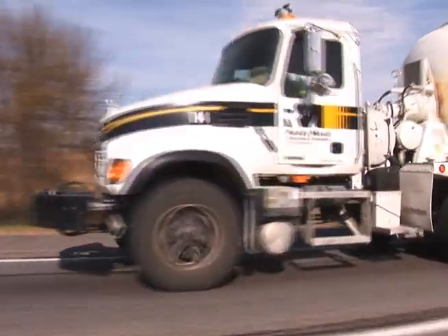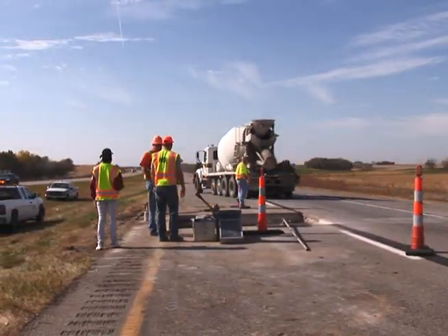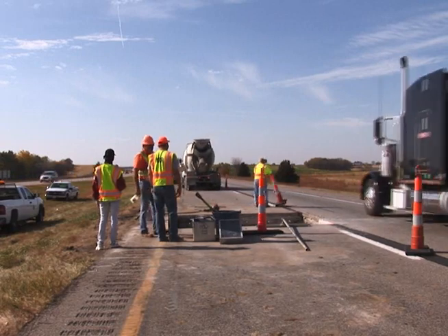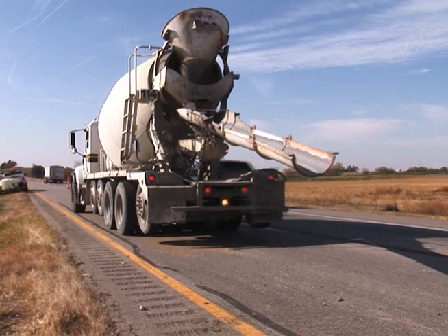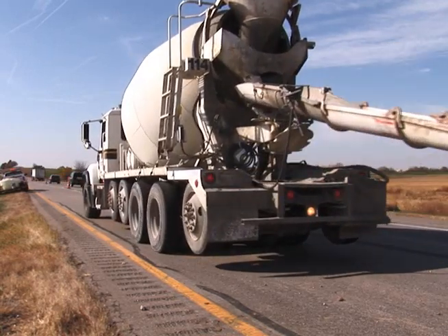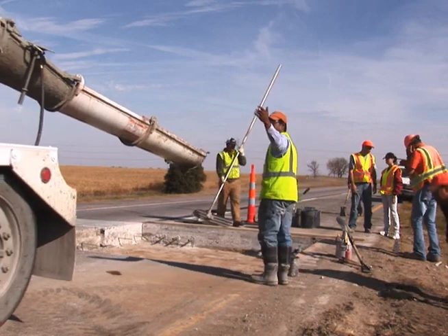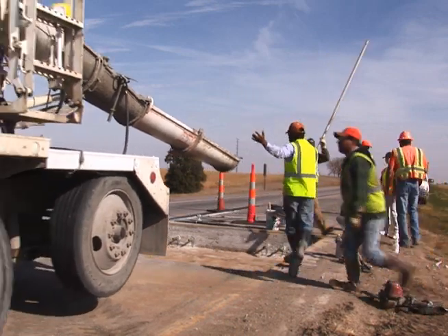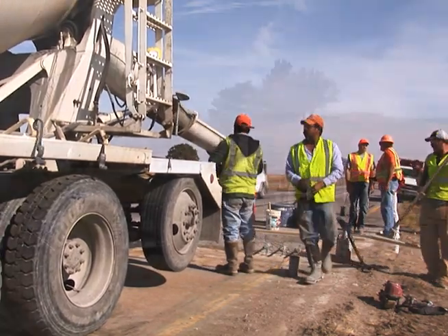The maturity method concept has been around since the 1950s, but it has been more recently that Nebraska fully implemented its use. The Nebraska Department of Roads has used this method for acceptance testing since 2001. The maturity method is a simple technique for predicting concrete strength in place of conventional cylinders based on the measurement of time and temperature history.